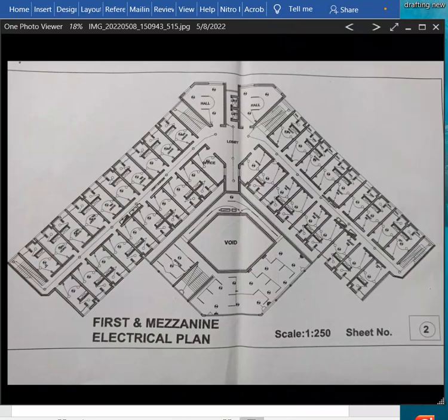What we're going to do is to calculate the requirement for the installation, the material required, and the switchgear requirement, and the cable, and sizing of the distribution board, sizing of rising mains, that is service mains, and the total distribution boards that are required for the installation. Okay, and also size the generator and the transformer and the other associated switchgear systems. Okay, we are also going to discuss the earthing system, the type of earthing that we are going to use.